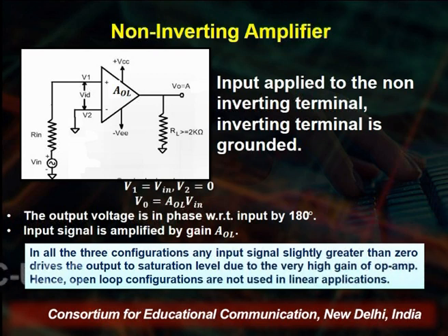As we understand from output characteristics of any amplifier, there are 3 regions wherein an amplifier is biased. Number 1 is the saturation region, number 2 the cutoff region, and number 3 is the active region. Only when the amplifier is biased at the active region does it amplify. However, if the amplifier works only at the saturation and cutoff regions, then the amplifier can work as a switch. That is, saturation means maximum current flows through the circuit, and at cutoff, 0 current flows through the circuit.